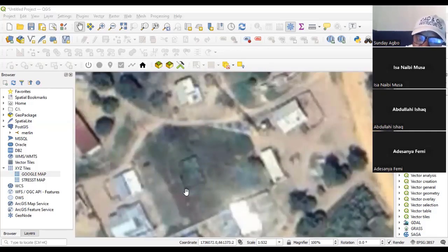Okay, now let's assume this point here is actually blurring, but I'm seeing a particular fence here. So let's assume this is where your building is starting from. Or possibly you are the one that is doing the layout, the site layout, and then you want to position the building somewhere. And possibly the building will be facing this direction. Now, you will just assume some point here, a particular point here, and pick it as a coordinate.